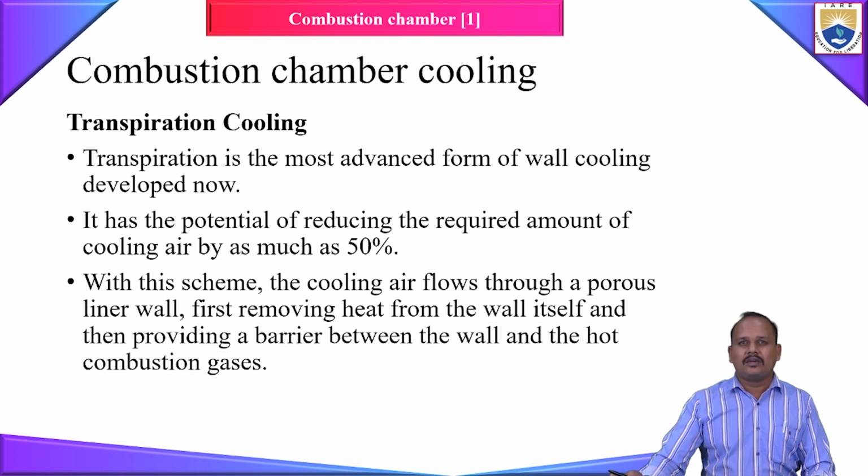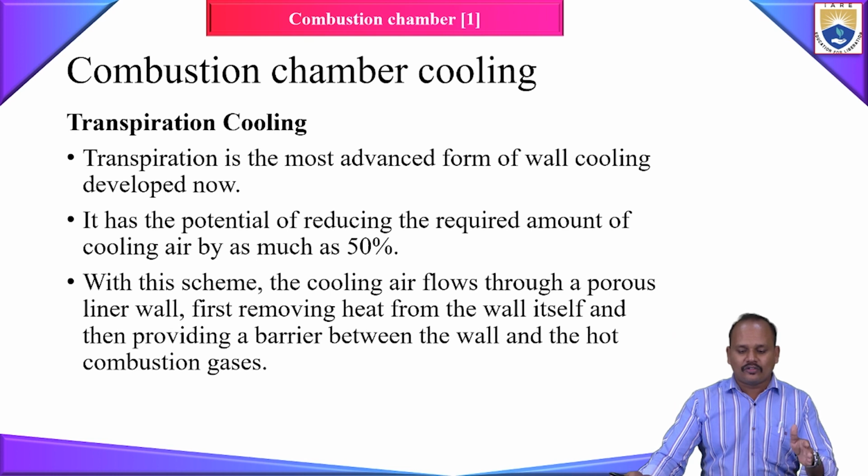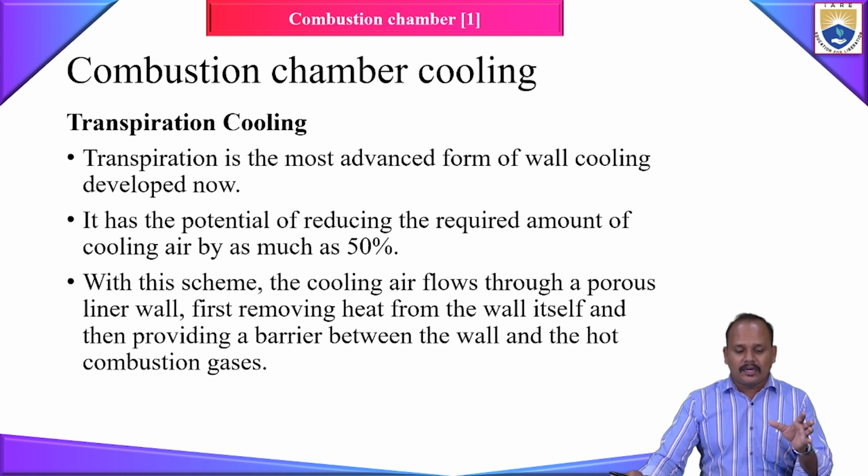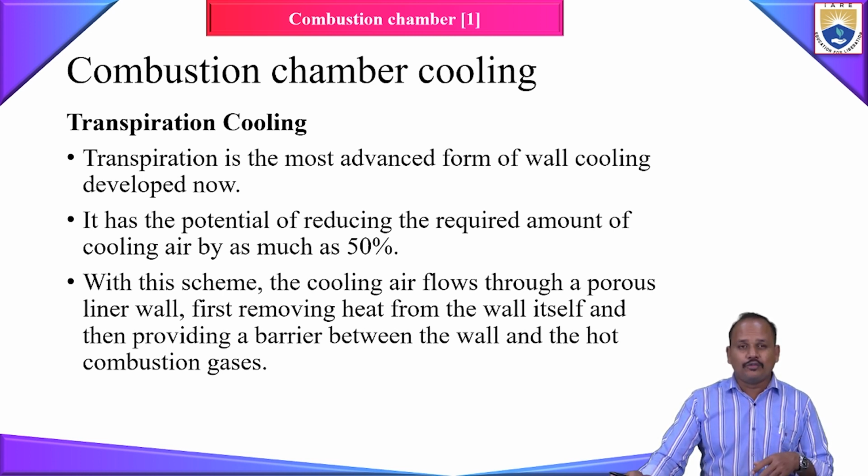The last one, which is the most advanced type and what most combustion chambers use nowadays, is transpiration cooling. This transpiration cooling is much more effective than the other cooling techniques. The reason I say it is much more advanced and mostly used is that the amount of air required for cooling is reduced by 50%.